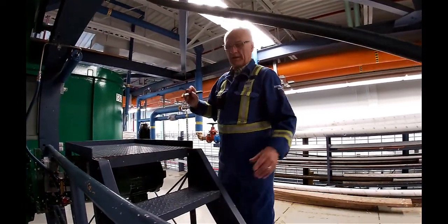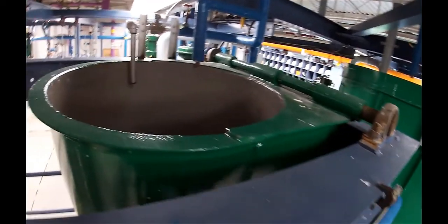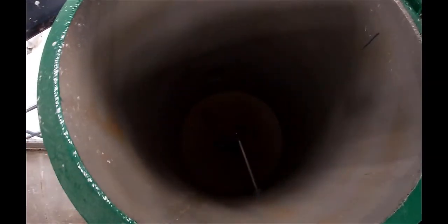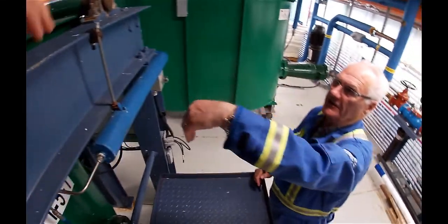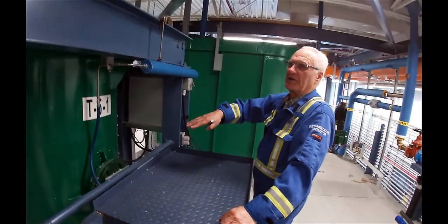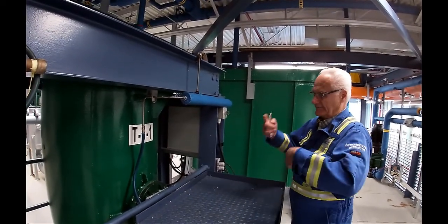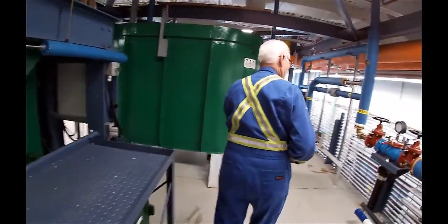All right, now, Raven, if you can go up that stairwell, take a look inside the tank. If you look into that tank, you'll see an agitator, a propeller in there, and that propeller is going to be turning later on, and that's what's going to mix our stock up. Mari is going to be loading sheets in here, and when she loads the sheets in, she'll put them in behind the agitator blade so that they actually get pulled through the agitator and get broken up. Now the stock sheets themselves are over here.